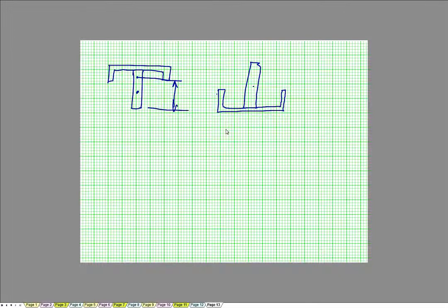I don't think I'm going to run through those, but it turns out that the distance 1 and distance 2 are exactly the same. The moments of inertia are obviously the same because they're the same shapes. You simply flip them over. You didn't change their orientation. You just reversed. So because distance 1 and distance 2 are the same, you get exactly the same numbers. It just might be a little bit easier to calculate this distance here because it's the thickness of a web plus 2 versus doing all the other stuff. And then the other one is already exactly what it was, 0.6, whatever that was. Okay, so those distances, they fall out just a little bit easier.